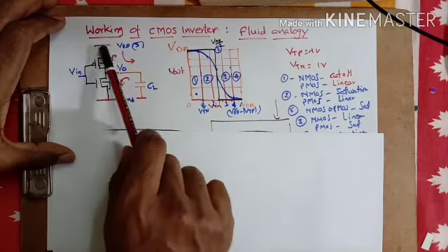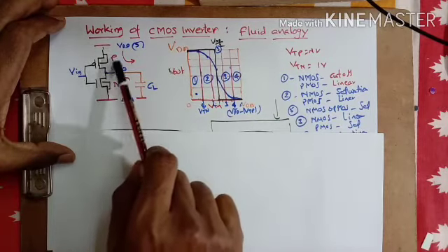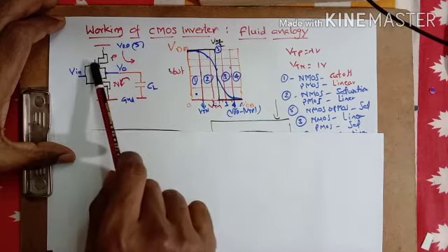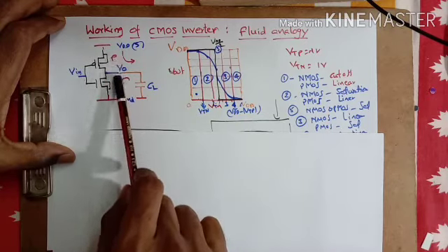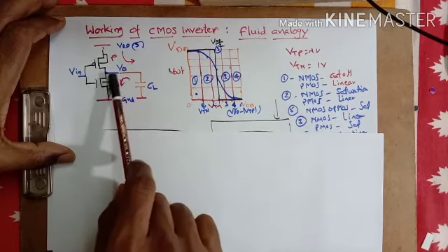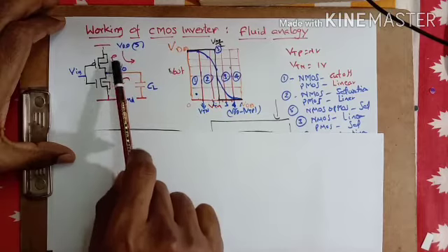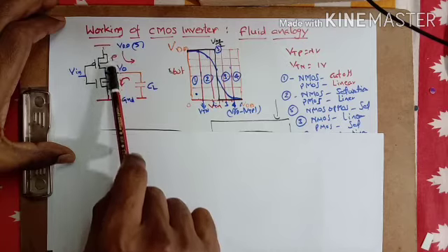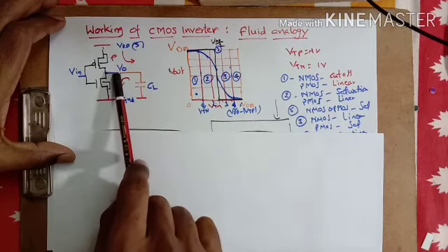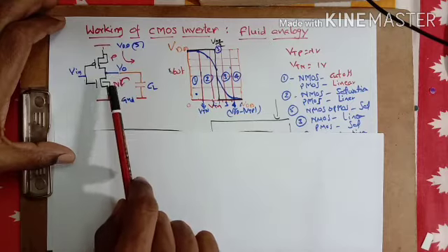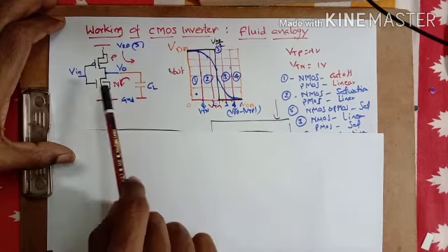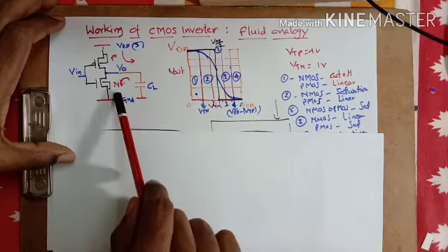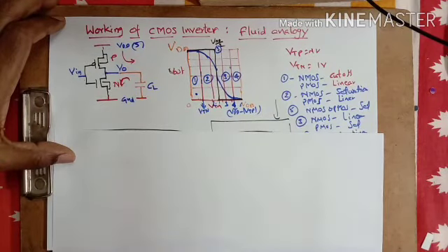So that is making it a saturation region, so the PMOS transistor will act now as a constant current source. It will pump constant current, irrespective of the node voltage here. The current does not change with the node voltage at the output here. So a constant current is passing through this. Now the voltage has to adjust to a particular level until the current now passing through the NMOS transistor, which is in the linear region, becomes equal to the current which is coming through the PMOS transistor, which is acting as a current source.